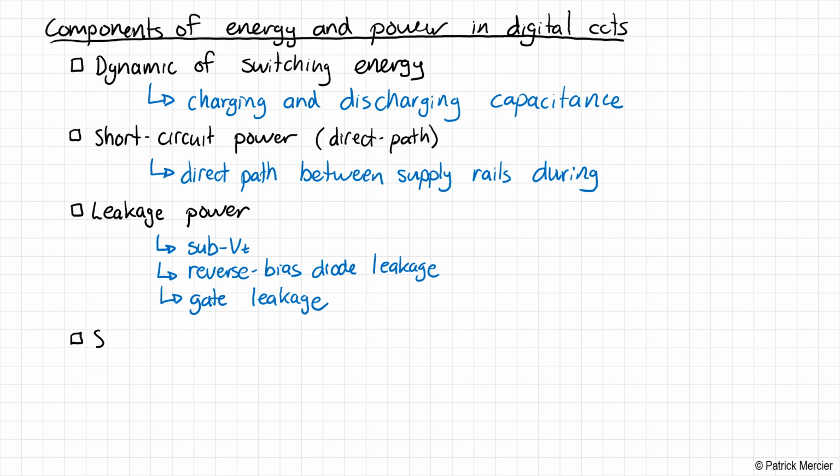And last but not least, we sometimes in digital circuits actually do have static power consumption. Now, we haven't seen a case necessarily where we would have that in a static complementary CMOS circuit, but we certainly have seen it in, for example, NMOS logic or pseudo-NMOS logic. So this would be, for example, when we have current sources in blocks we call sense amplifiers.